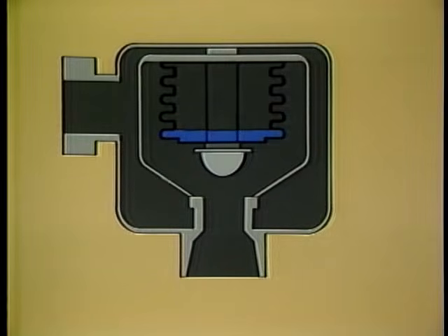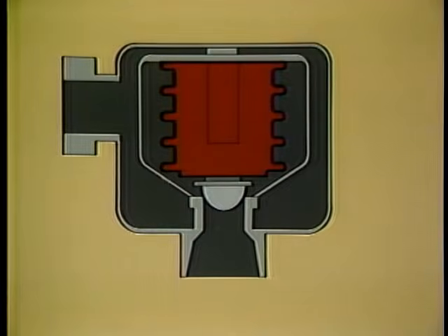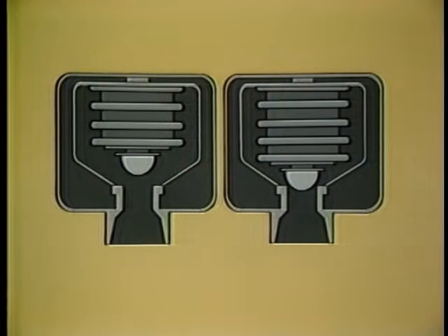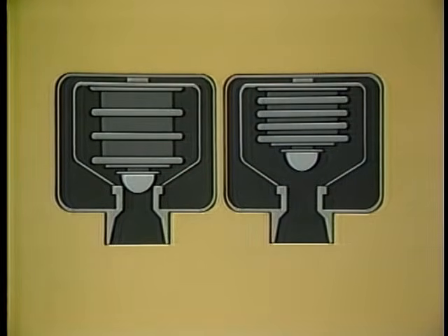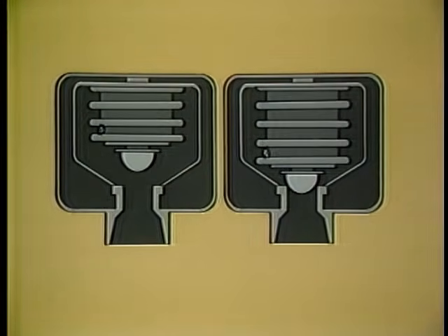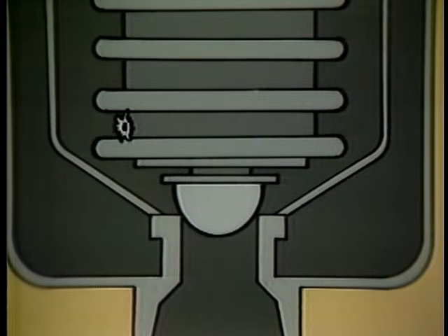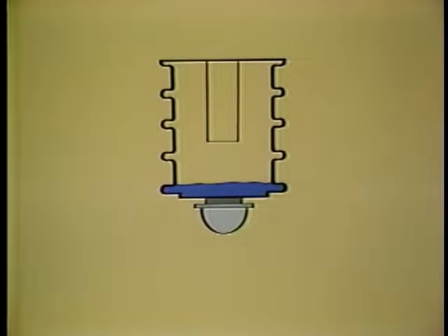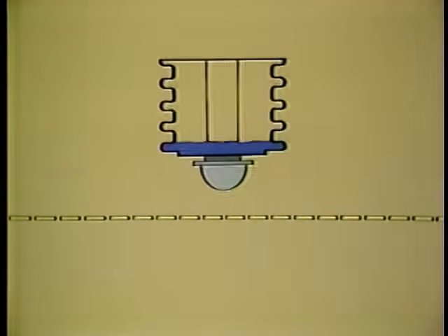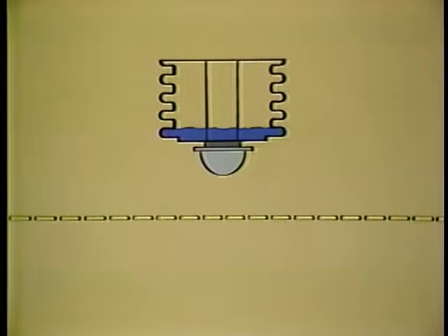When the bellows charge vaporizes, the pressure inside the bellows increases. A sufficient increase in this pressure expands the bellows to seat the valve. There are two methods of constructing a bellows trap, which determine, among other things, how the trap will fail, open or closed. In both methods, the liquid charge is added and then a vacuum is drawn in the bellows, compressing it to an internal stop.